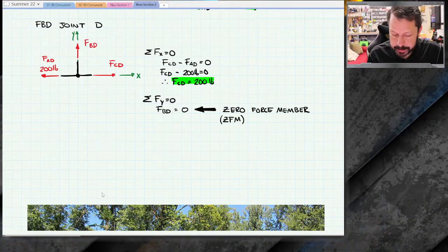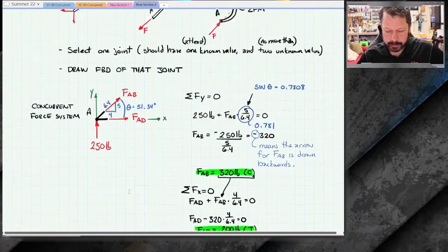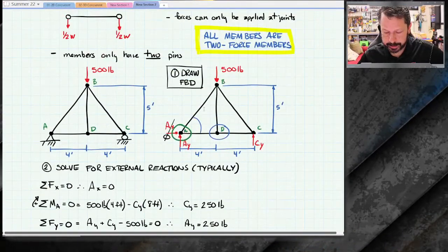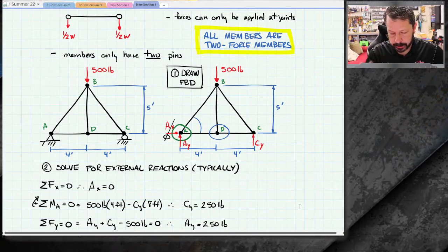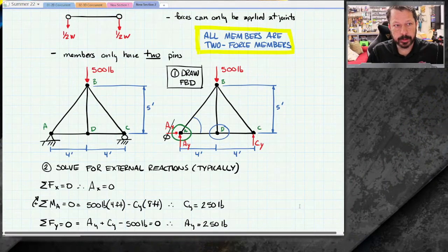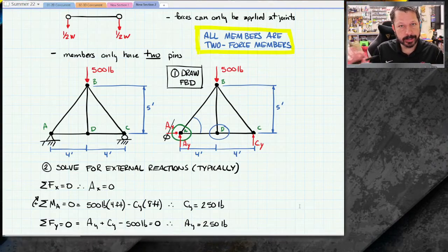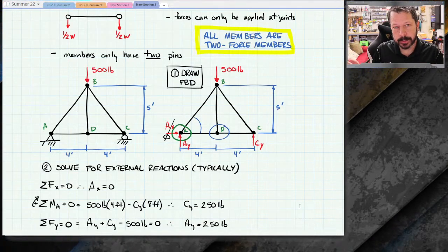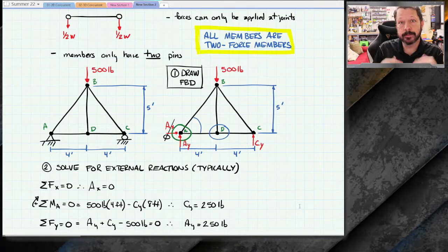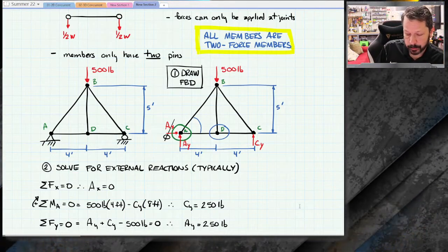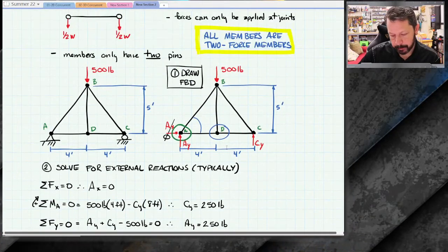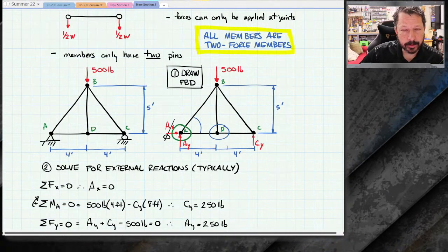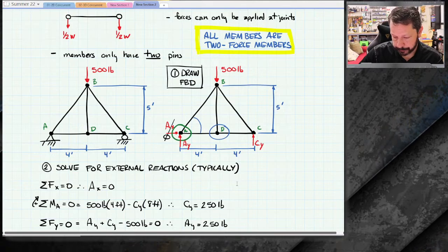And it doesn't mean that we can just totally leave it out of the truss, you know, just take out member BD. It just means that under this particular loading situation, with everything being rigid, so nothing deforms, nothing changes shape or anything like that, so it's under a very simplistic set of rules, that member BD doesn't have any force in it, or it's a really small amount of force.